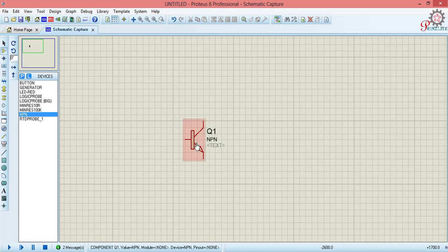First of all, to use the transistor as a switch, we place our resistor at the base of our transistor. Assume you know what a transistor is. A transistor is a 3-terminal device. This is the base, the emitter, and the collector. We take output from the collector when using a transistor as a switch, and our input from the base. And the emitter, of course, is connected to the ground.